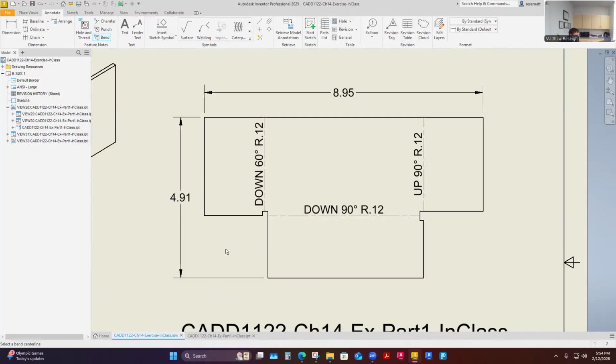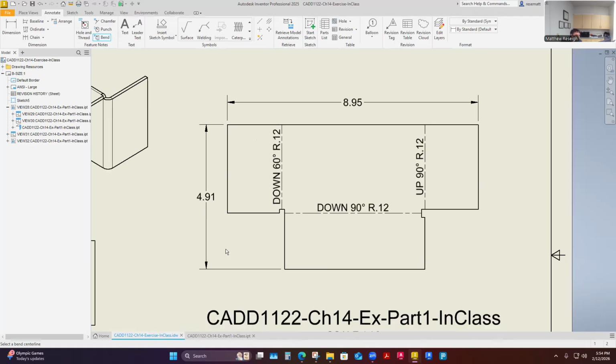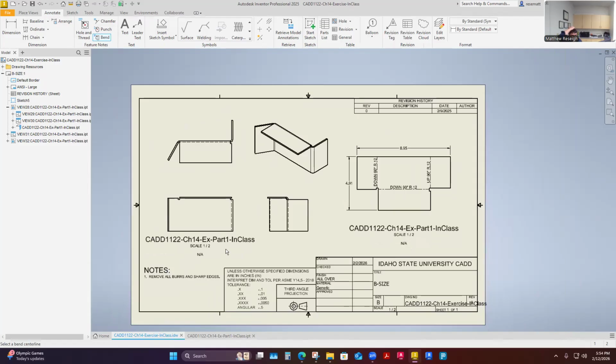So everybody in the system has a different need for different prints, and you have to cater to those needs, especially when you're working for a company that has in-house engineering drafting and in-house manufacturing. You're preparing prints for machinists, for material preppers, for prefabrication technicians, and for welding technicians. So your prints have to incorporate everybody's needs essentially.